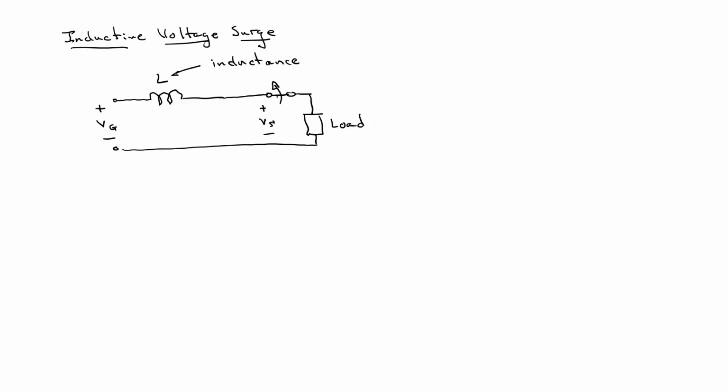after it opens up. The underlying assumption in this model of the transmission line as a single inductor is that the entire power line shares the same current, which I'll call I. So when I open this switch, I stop the current everywhere in this line simultaneously. This is going to cause problems since an inductor stores energy as current and it's not possible to change energy